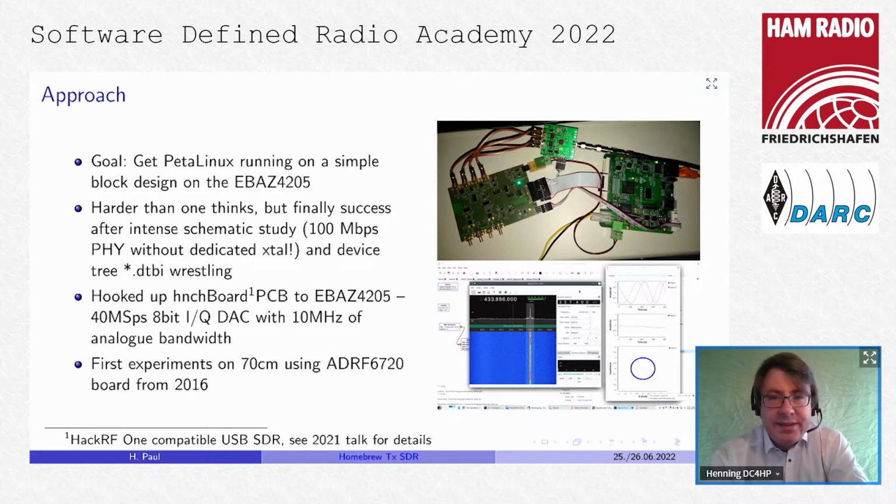And I hooked up the transmit part, the DAC part of this board, with a flat cable to this Bitcoin mining controller, and also hooked up the I2C. And then I was able to plug together a block design that was able to play out samples received over Ethernet, over this parallel bus, into the DAC board. And after a few days, I had it running so far that I was able to generate the first signals